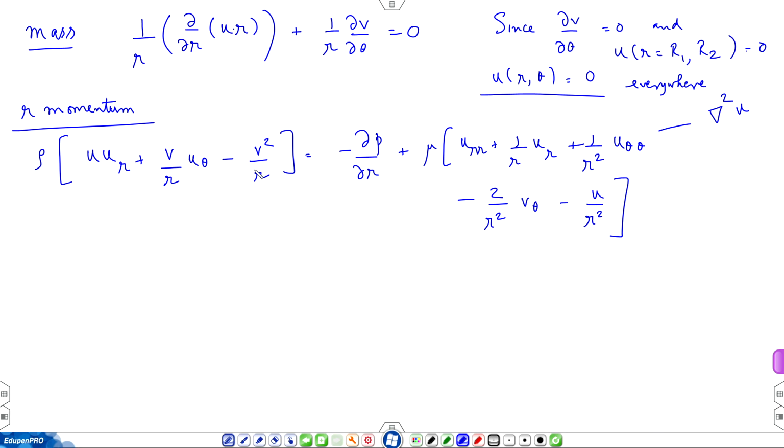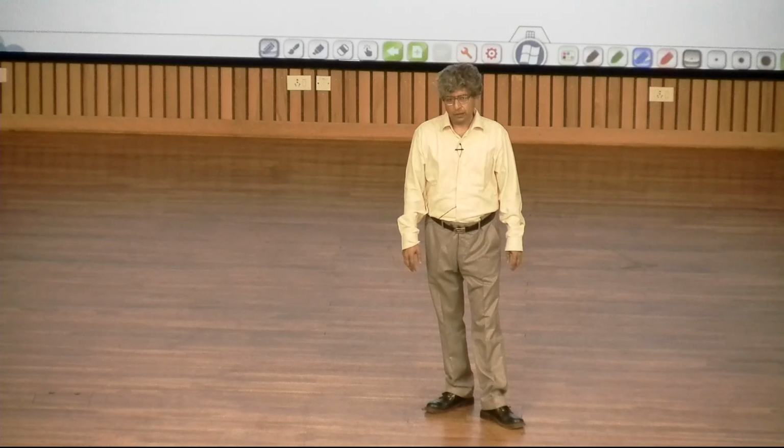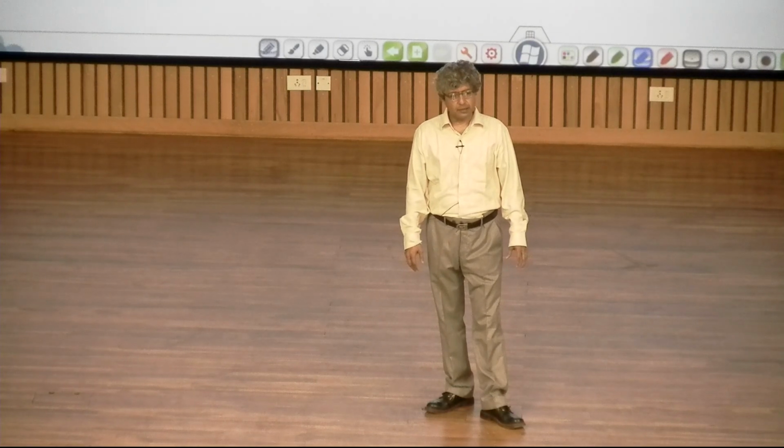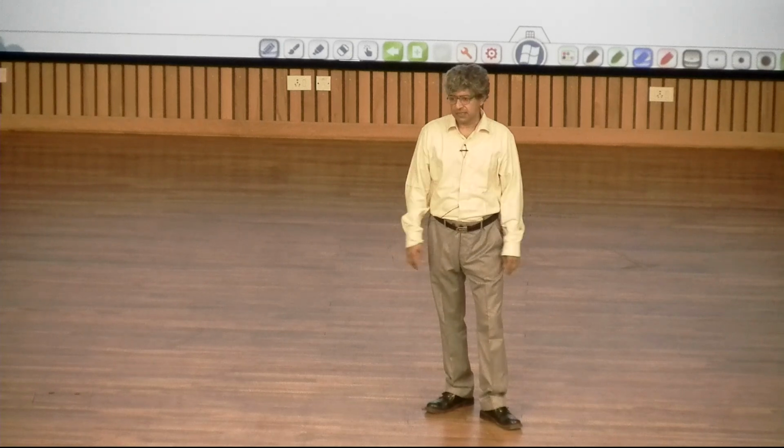When you do courses on, let us say, rigid body dynamics or particle dynamics, all those acceleration terms are externally added. But when you work in coordinate free form, they appear intrinsically as curvature terms. You do not have to prescribe additional acceleration terms.